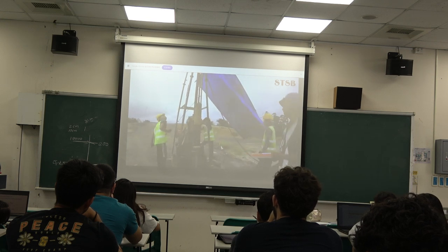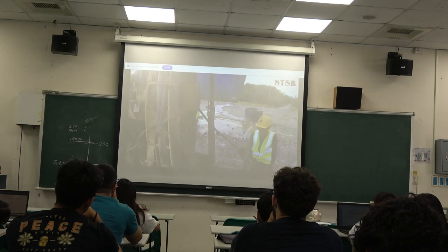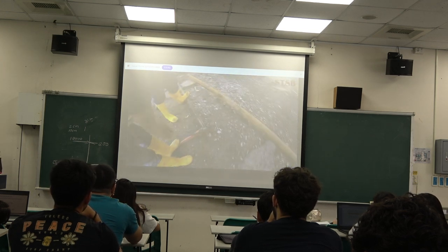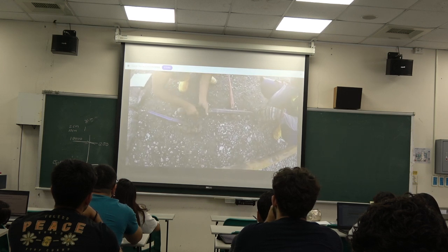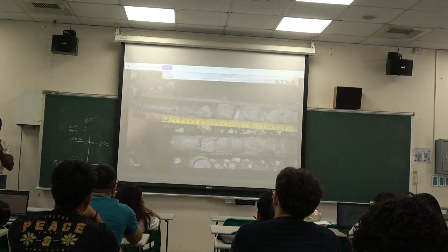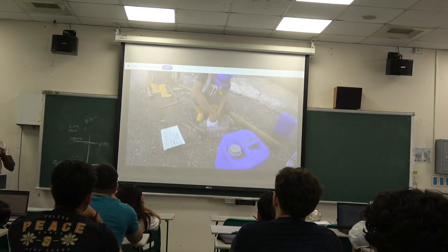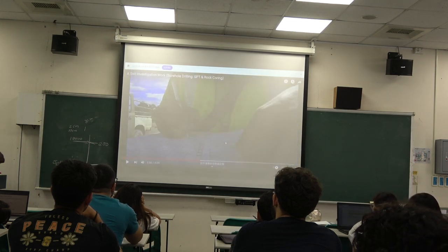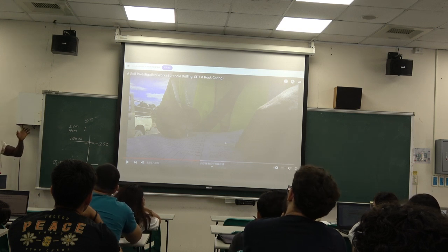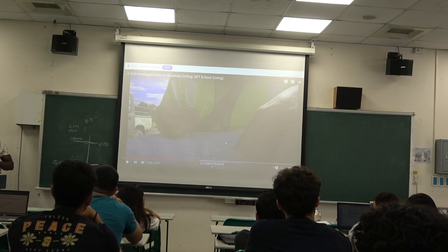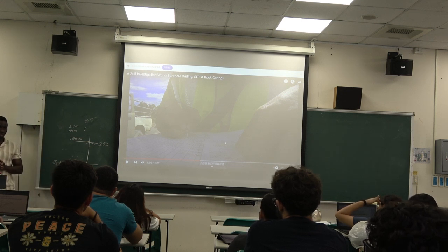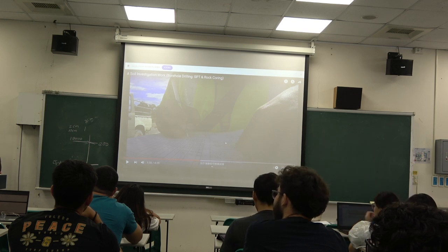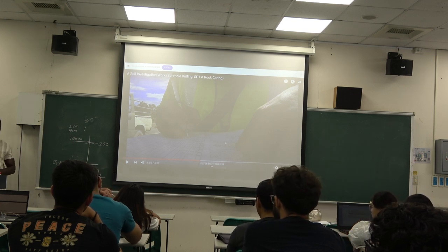So you can see it's going up to that specific height. Take it up to the specific height, and then you release it. Because you put the tube inside, inside the tube you can also get some soil samples. But mostly these soil samples are just used for classification, to give you an idea as to what the soil profile at the site is. Because you are using the hammer and hitting it, bam, bam, if the soil you get is highly disturbed, it's highly disturbed. So most of the time, the soil sample collected is just used for the classification.